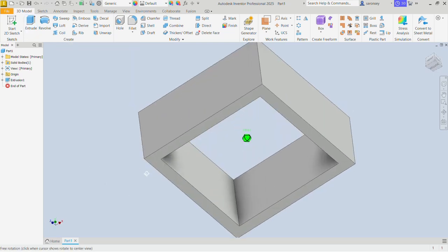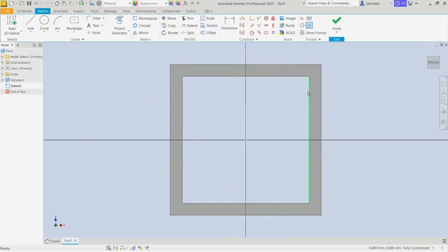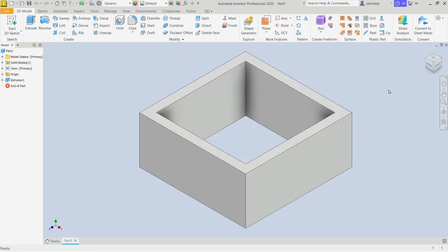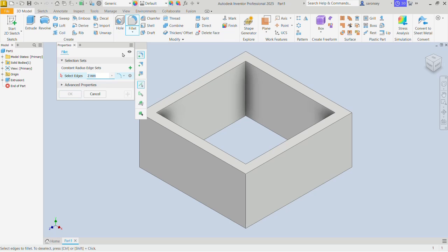Now I'm going to turn around this model. Let's select this face and create another sketch on there. Even before we do that, let's just undo and get the isometric view. Let's go ahead and apply some fillets before. And so the fillet command, the fillet radius will change to 10 and apply it to this edge, also this inner edge.